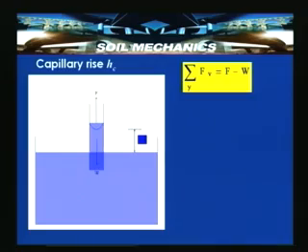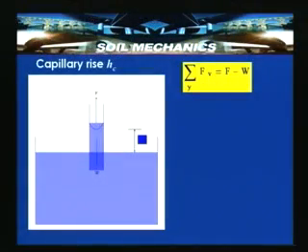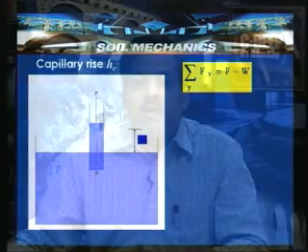Now, if you take the vertical equilibrium, sigma Fv is equal to F minus W. So, the capillary rise is calculated at which F is equal to W, that is, the vertical force with which it is pulled is balanced by the self weight of the water column. So, to that height it will rise and then it will stop at that particular point, that is the Hc, which we are going to obtain from this direction.